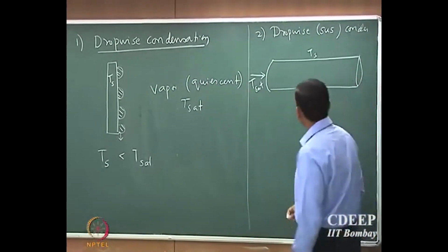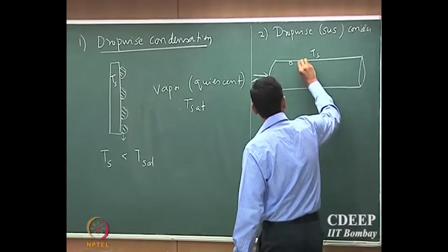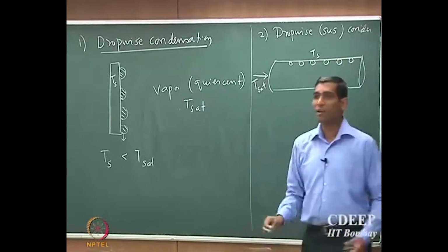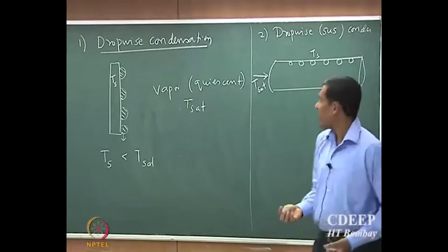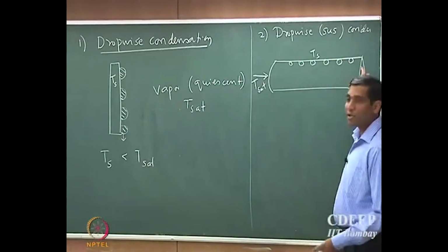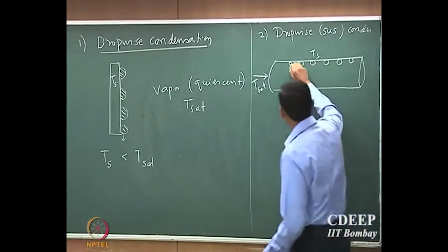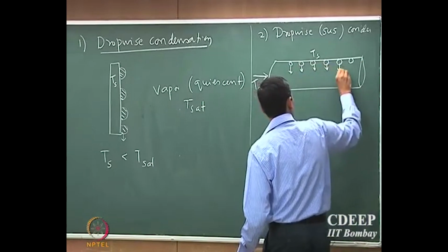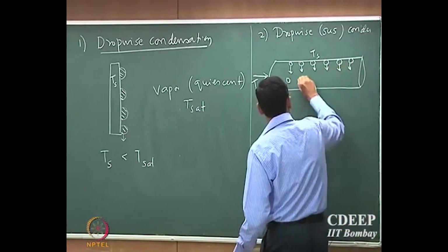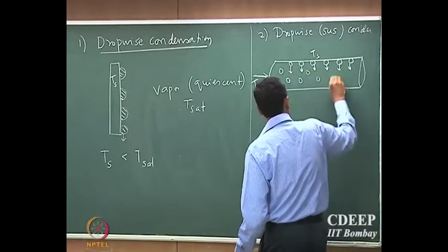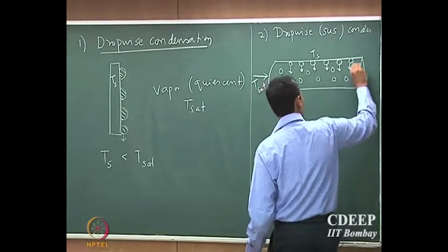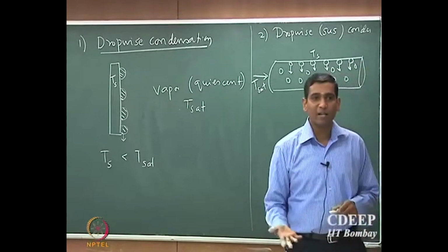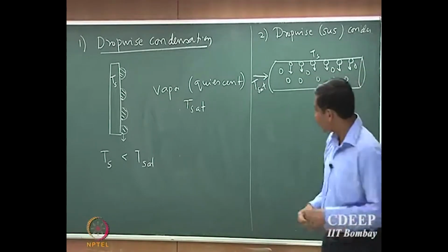Okay. Now the drops will form along the curved surface of the tube, and note that this is a horizontal tube, right? So they will detach and then they will drop into the vapor. They will all detach, and so now you will start having these drops which are suspended inside the vapor. So this is the dropwise suspended condensation process.